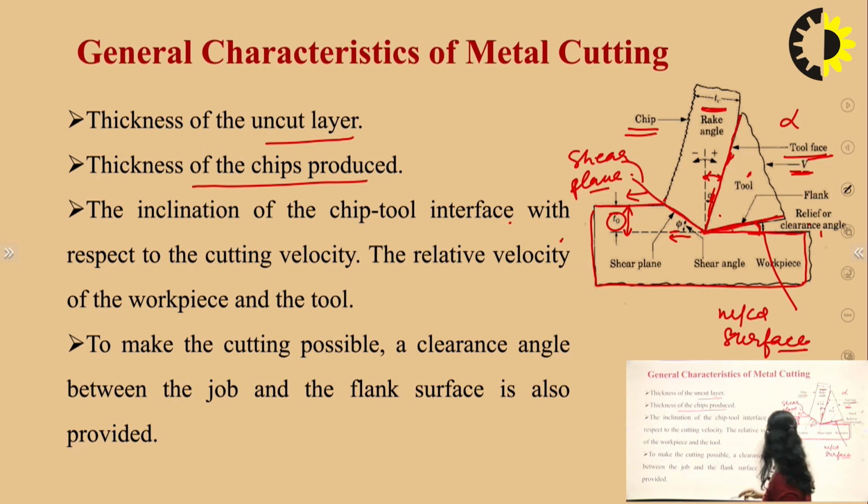the inclination of the chip tool interface. Chip tool interface is this surface. This surface is the chip tool interface with respect to the cutting velocity. Cutting velocity is this one. The relative velocity of the workpiece and the tool. There will be a relative velocity between the workpiece and the tool also.